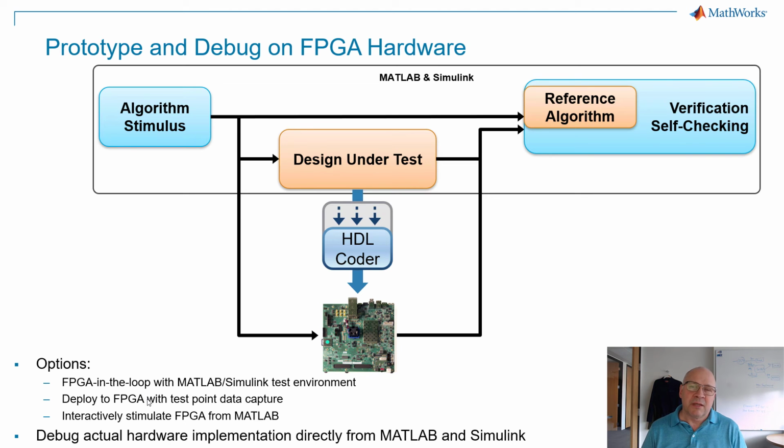Now, people always want to know, how fast does this run? Well, it's always going to be design dependent. You are limited by the communication between the computer and the board. For most cases, that's Ethernet. For some, we may only have JTAG support. For a few, we actually have PCI Express support, which will be faster yet. And it depends on if there's feedback and other elements, but you may get some good acceleration compared to just running with an HDL simulator.